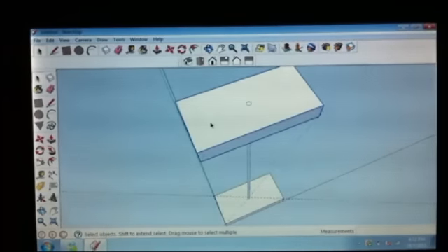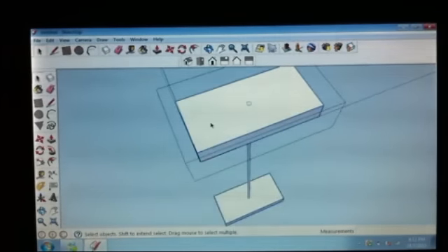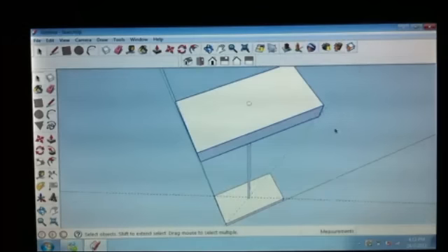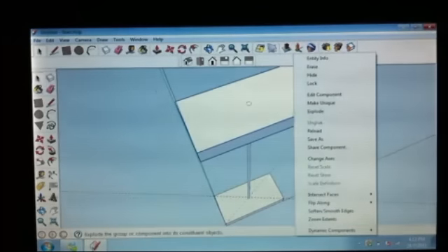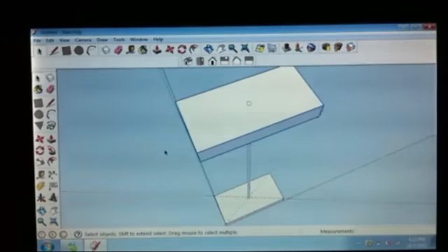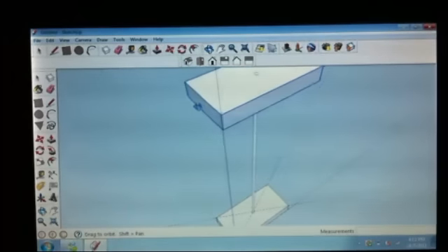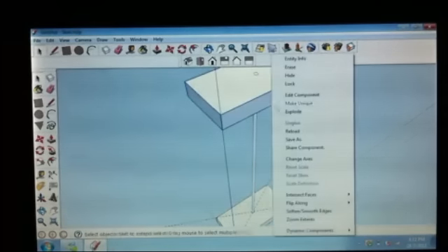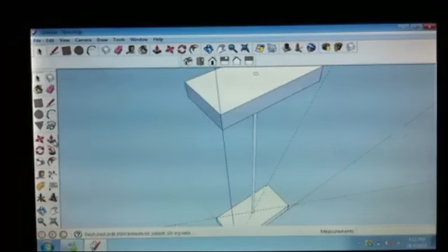You can make changes by exploding this part here. You explode it. Now let's try and see. When you pan it, maybe you want this to be smaller but still a base. You push and pull. Oh, you see it can't. Why? Because this was made a component. So try again. You explode it again. Let's test it out again.